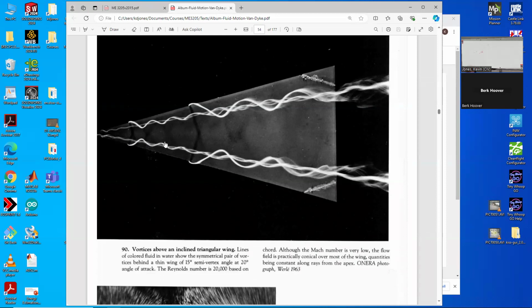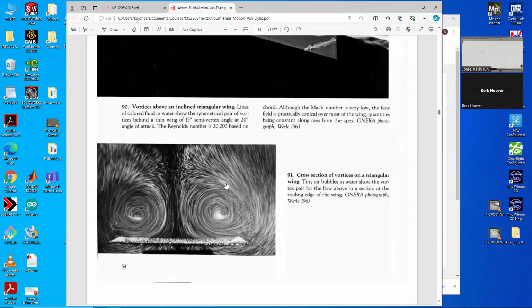So normally, if this was an unswept wing, it would totally be stalled, be useless. But with the swept wing, these vortices reattach the flow. You can sometimes have a pocket in the middle that's separated, because the effect of the vortices doesn't reach super far. So at certain angles of attack, you'll have some regions that are good, some regions that are not. And let's see, here's a side view of it. They're cranking like this, so they're actually throwing material down on the top of the wing in the middle here.